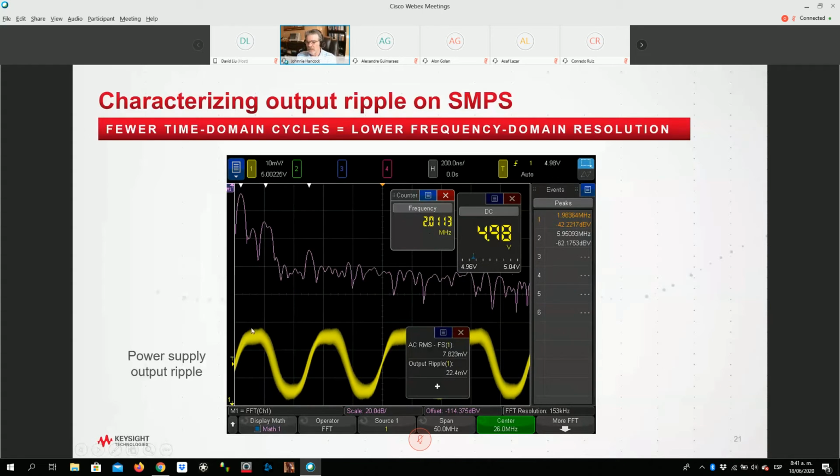But also look, there's all sorts of fuzz, or what looks like noise, riding at a much higher frequency than the 2 megahertz switching rate. And so I've turned on FFT to see if I could uncover what's going on in this power supply. You can see the first peak here is the switching rate. The second one is kind of jumping around a little bit. Maybe, I don't know if you can see it, but it's around the third harmonic, so it's around 6 megahertz.